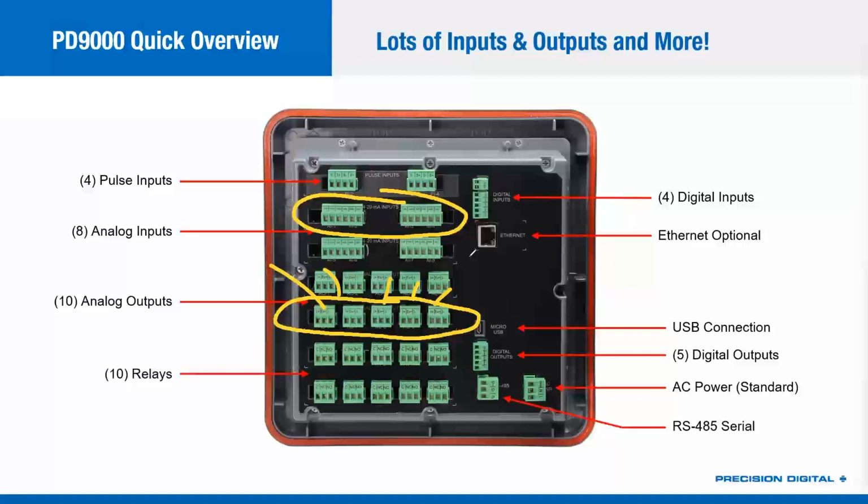The main exception I've run into is gas detection. Some gas detection units can run off of 200 milliamps. Some, especially including inrush currents, become real current hogs, and they want their dedicated 24-volt power supply to be able to provide them 500 milliamps, an amp and a half sometimes. And so if you're doing gas detection, you want to keep a good eye on that. But if you're not talking gas detection sensors, I found that 200 milliamps is essentially enough to run almost any transmitter I've run into.